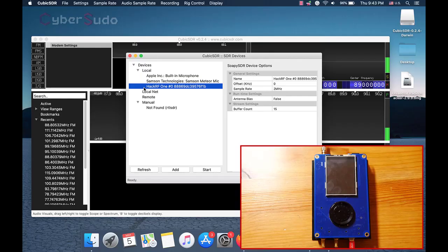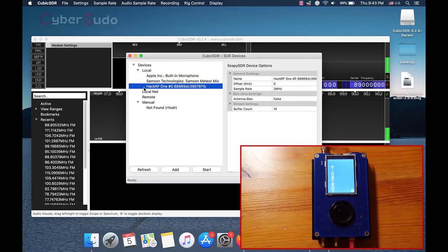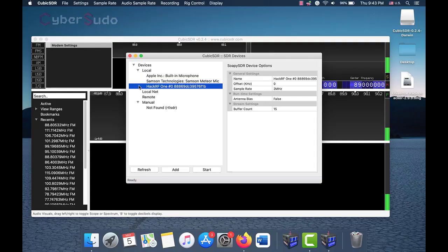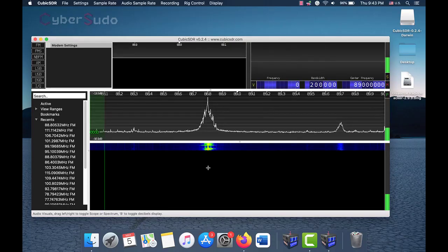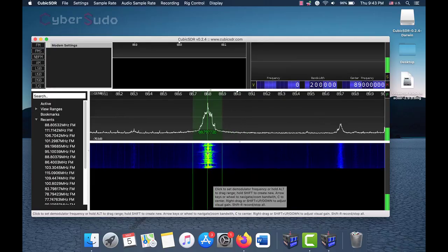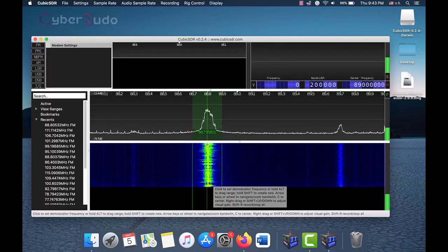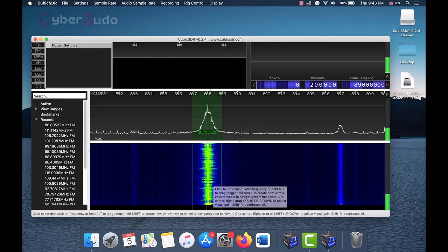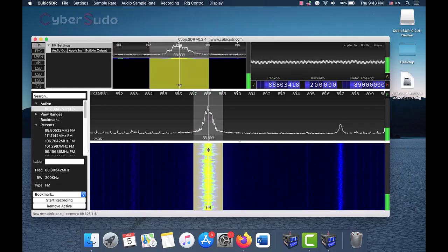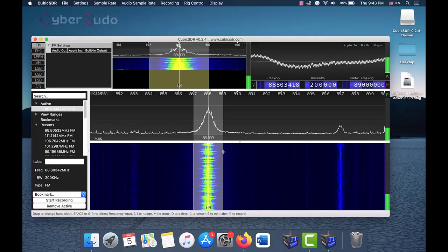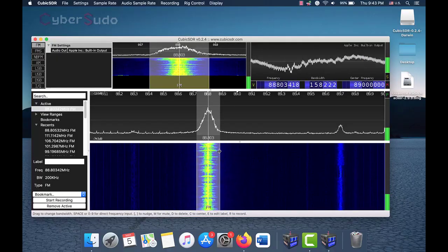And this option is going to allow our HackRF to run on our laptop or PC instead of running in the Portapack. So first of all, we need to select the device that's going to listen to the radio frequencies out there. Once we click on it, we're going to say start. And you can see that there are some signals in here, like in here. And this is the 88. For example, right now we are on 88. Once I click on it, it's going to run. Now, because I'm in Germany, that's why you are listening to a German radio.